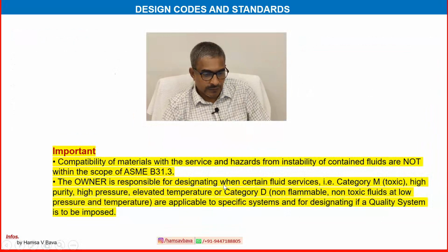Important information: compatibility of material with the service and hazards from instability of contained fluids are not within the scope of this ASME B31.3. The owner is responsible for designating when certain fluid services, that is Category M toxic, high purity, high pressure, elevated temperature, or Category D non-flammable, non-toxic fluid at low pressure and temperature, are applicable to a specific system, and for designating if a quality system is to be imposed.